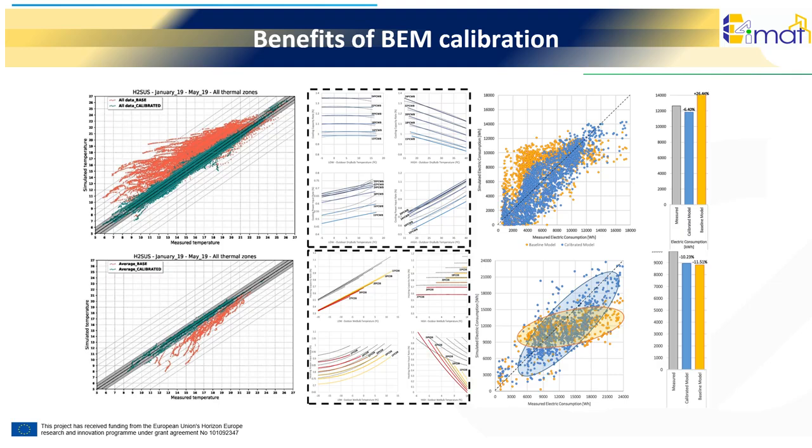The importance of calibration lies in generating an accurate model, one whose simulation emulates reality. A building energy model that captures the indoor climate behavior by producing simulated indoor temperatures related to the actual building, while reducing the model's performance gap and demanding similar energy consumption that the building has in reality. This enables confident use of the model for forecasting energy savings, assessing design options, improving building operation, and validating interventions. In essence, calibration improves a BEM into a reliable decision-making tool rooted in measurable reality.